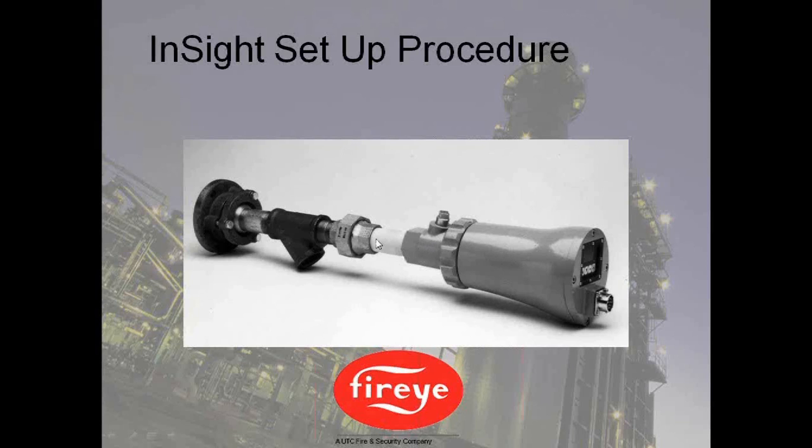If we had a low pressure application, we wouldn't need the sealing union or the Y. We could come with this nipple straight into our swivel, and we have a 3/8" port that's built into the flange to provide cooling air.